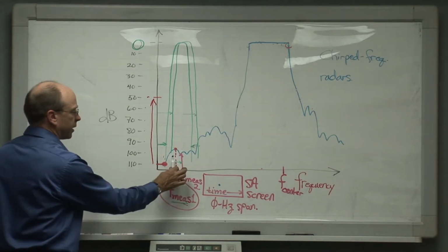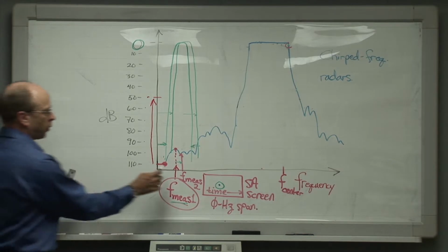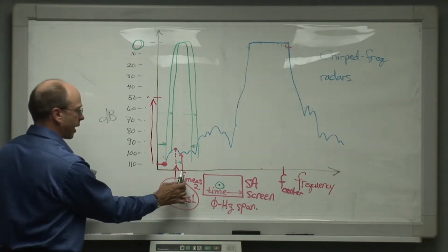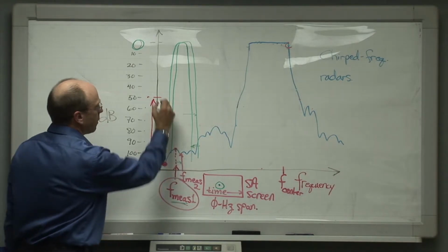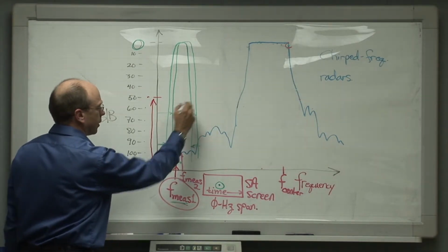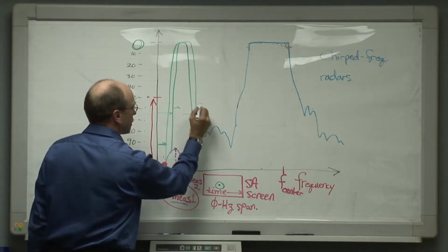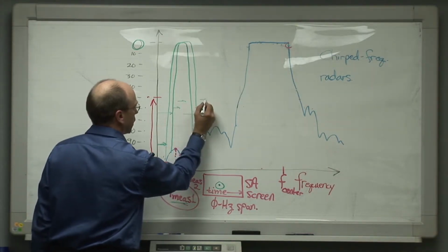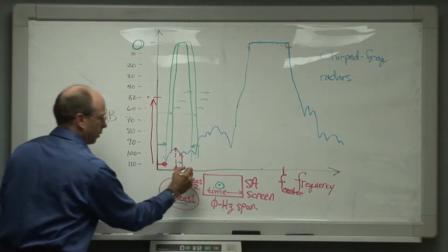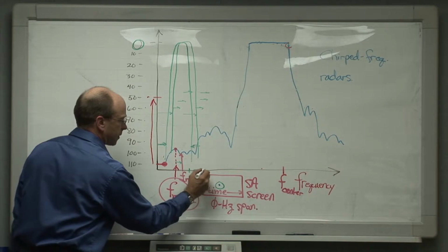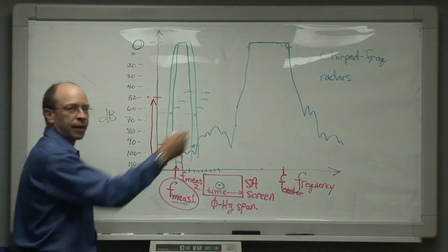We make a measurement on a single frequency, we get the data for the amount of power that the radar is emitting at that frequency, we step our measurement frequency a little higher at a later point in time, we'll talk about how much higher later, and then we move the bandpass filter along with it. And now we continue this sideways stepping action with the bandpass filter and with the tuned frequencies on which we're performing a measurement, increment by increment by increment.